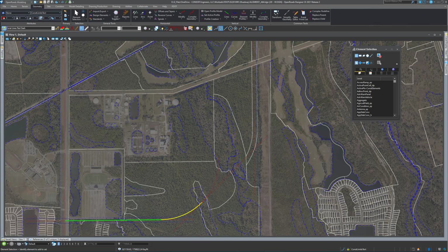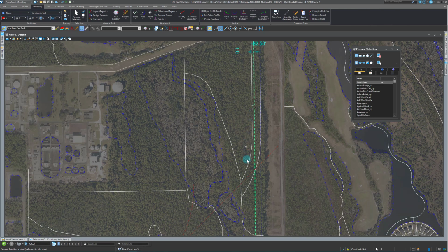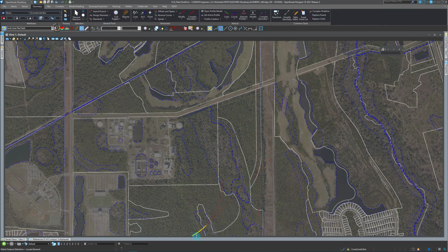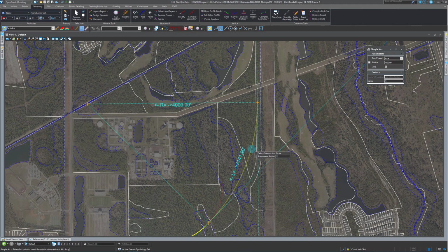And now I know that the next arc radius is also 1375 between this line and this line. And again, you can see I set up my construction line here along this right-of-way line, and the plans are defining the offset here for the center line, so that I'm able to come in and just do my normal arc between elements. 1375.